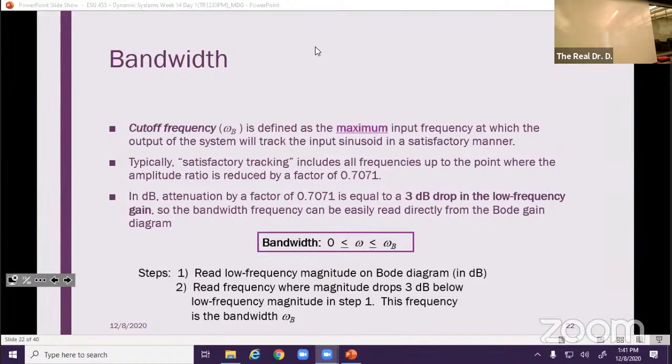It's all about this range of signals that we can operate in, right? You're trying to give the range of inputs, the range of frequency inputs, which this is still accurate, right? Before we attenuate too much, right? So basically, under these conditions, you wouldn't want an input frequency that's higher than your bandwidth, right? Because then you start to lose amplitude and your phase shift becomes too large.